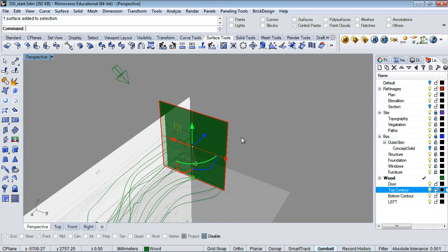So construction planes are relative to each view. So if I set the construction plane in perspective view, I can have a totally different construction plane in the left or right views, all my other different views. So sometimes when you start messing with construction planes, you have to kind of remember, and always look down here to this bottom corner so that you can get an idea of how that's actually laying out.